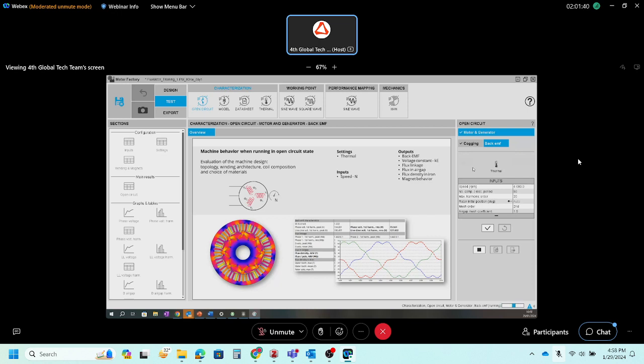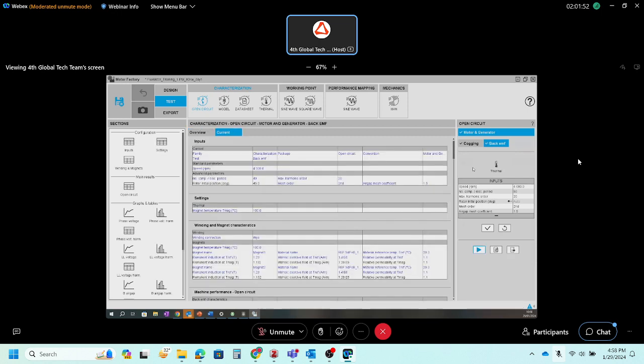These two parameters refer to the mesh that the embedded finite element model has. By default we have a second order mesh, so the model is quite accurate, and the air gap mesh coefficient is 1.5.